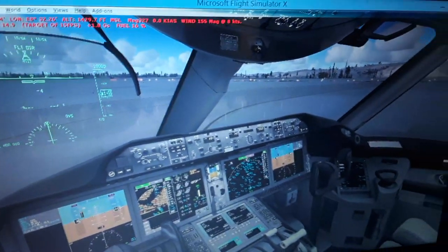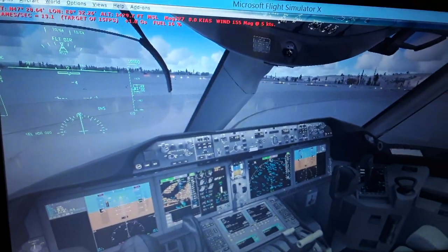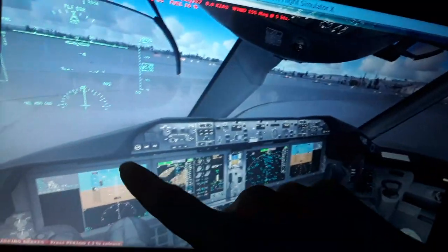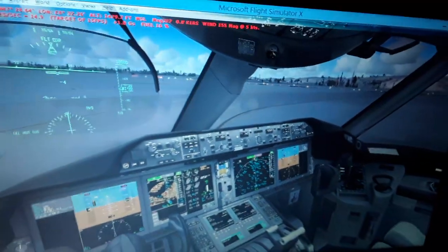And we have to be aligned with the magnetic north pole heading of 136 degrees for the runway. We have the runway 14 in Zurich International Airport, LSZH in Switzerland. So we have to be aligned with the runway heading. You will see later when we're going to be flying the ILS localizer displayed over here in the primary flight display. So also we have the angle of attack, we have other indications.